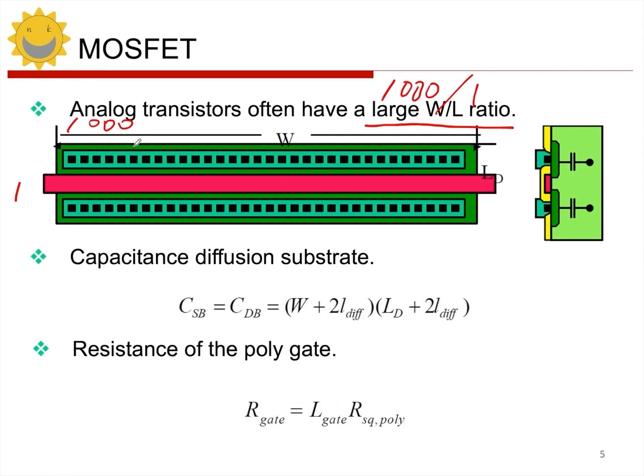Mainly 2 issues. The first one, you can see the source drain area is very large. A whole drain path will be very large, which is a problem. If the area is large, the parasitic capacitance will be relatively large, because we know that there is a reverse bias junction between the source drain area and the substrate, right?